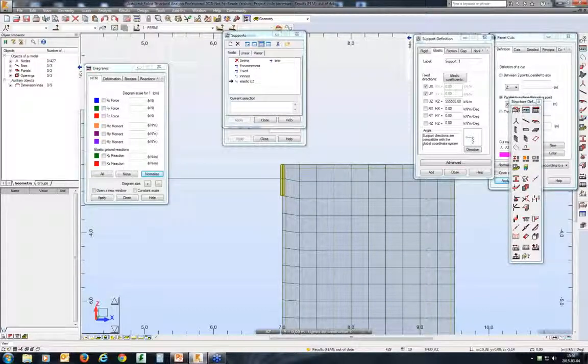And again, let's reverse the question. What I'm trying to say is, first of all, think what kind of results you want to obtain. If you model your wall as a surface and then you want to use it for column reinforcement, that's not going to work. In this case, you simply should model this wall as a column.